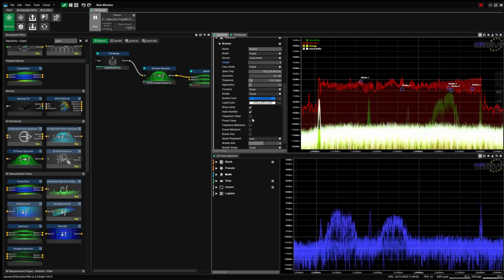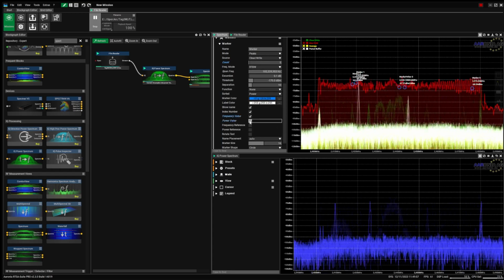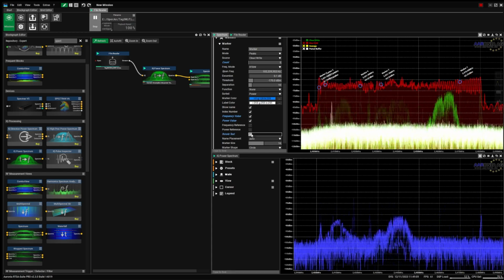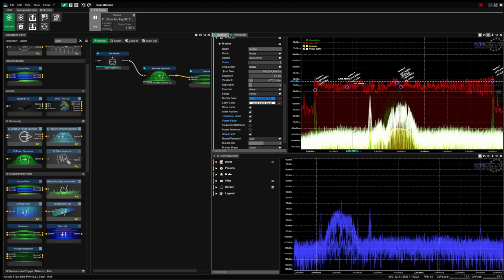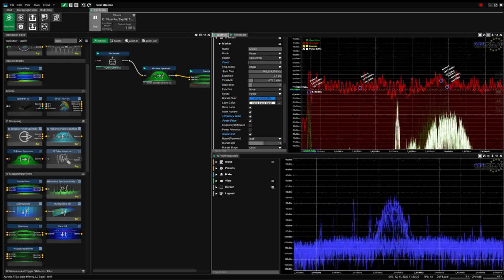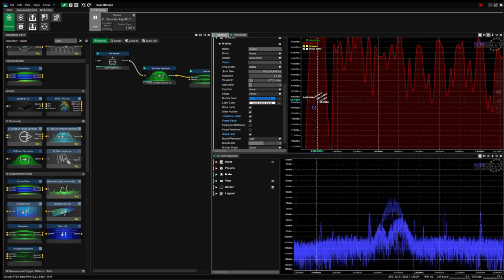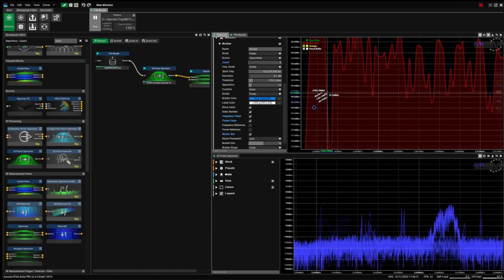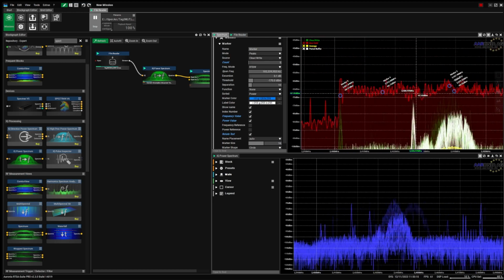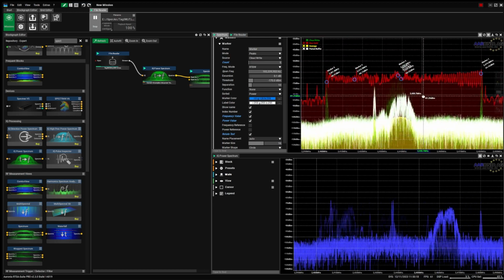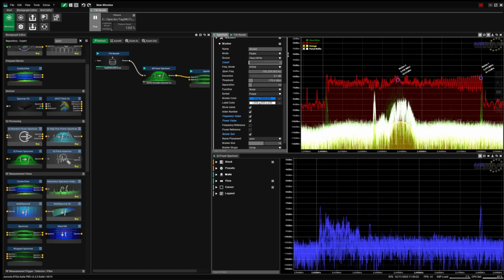and I want them to include frequency value and the power value, and rotate the text a bit. If I pause this right now, I had like a marker 5 here. So 2401.84 megahertz at minus 68.97 dBm. There. So I can remove a little bit of these markers.